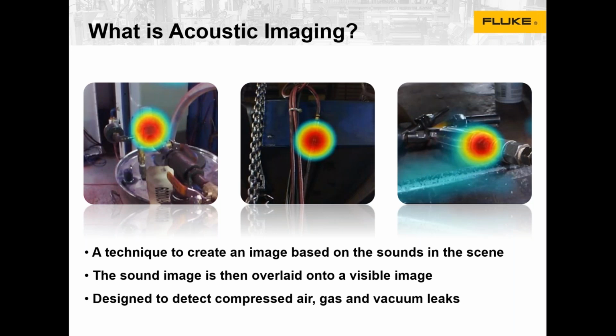And creating a sound or a leak that the acoustic imager is picking up on. In the middle picture, you've got an air hose or a drop down there, and you've got compression fittings, and you've got a bad connection there. Whether you need new hardware or you need to wrap it in Teflon tape or whatever the case may be, there is a leak that can be fixed and addressed there. And then on the far right-hand side, similar, just a different part of that air hose drop down where you've got the actual handle connected and you've got a leak there.